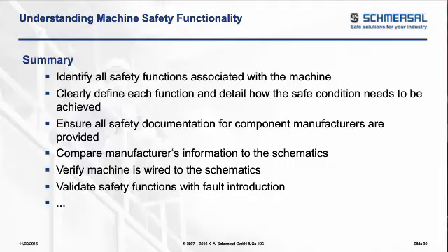Different drive manufacturers not only do it differently, but even within the same manufacturer, based off of the series of drive and the circuitry inside, there might be different ways of actually integrating safety in, which doesn't use the same nomenclature or labeling on the drive. You really need to have all the documentation for everything that you're doing related to that safety function.